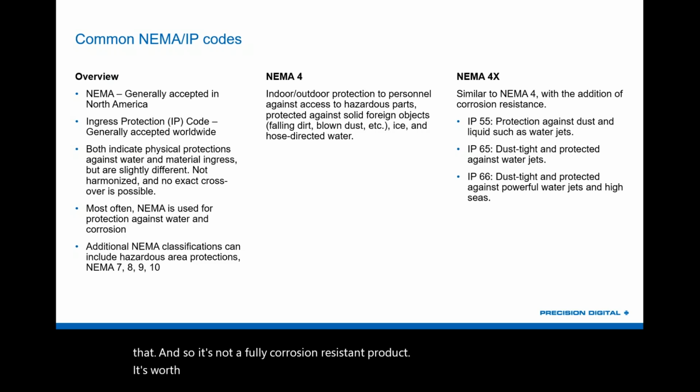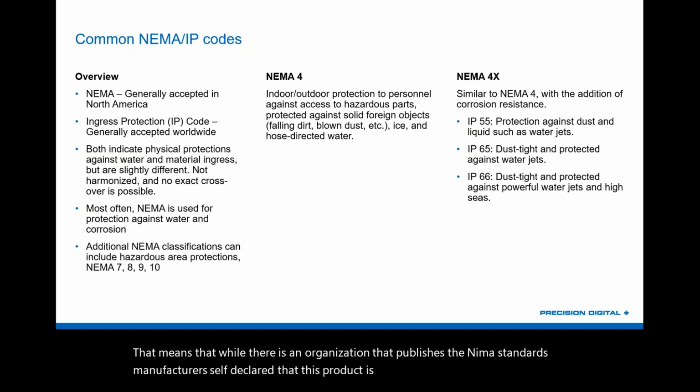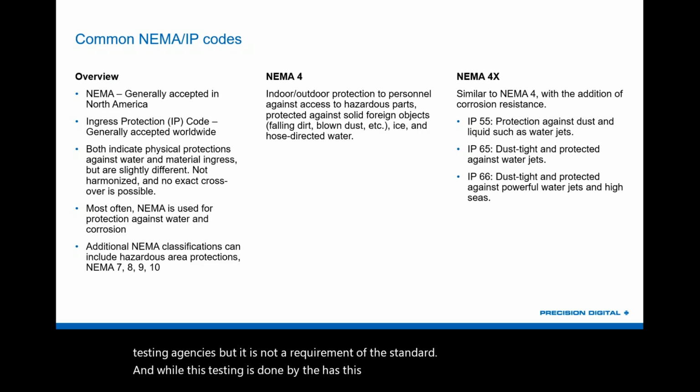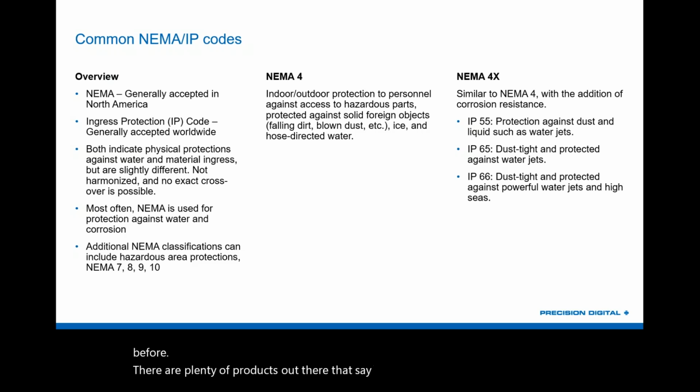It's worth noting that NEMA ratings are a self-declaration. That means that while there is an organization that publishes the NEMA standards, manufacturers self-declare that this product is a NEMA 4X product. Now, hopefully, like Precision Digital does, they send this out to be verified by third-party testing agencies, but it is not a requirement of the standard. And while this testing is done by the hazardous area testing agency, so for example, FM will want to test to make sure the product is NEMA 4 before they say it's NEMA 4, there are plenty out there that say NEMA 4 that are not tested by FM at all, that are just safe area products.